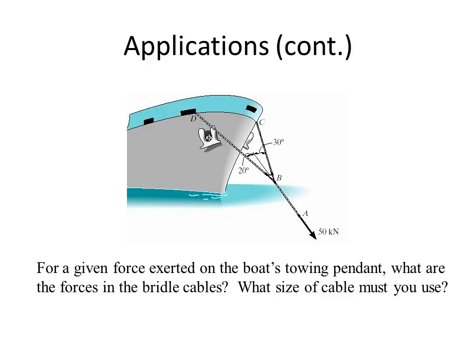Another example would be to look at this boat's towing pendant and decide whether or not the forces in the cables are going to exceed the strength of the cables, or are going to be within the strength range of the cables, and decide whether or not this is a stable setup. You might also use it for design of picking what size cable you'd need to have in order to keep this configuration stable.